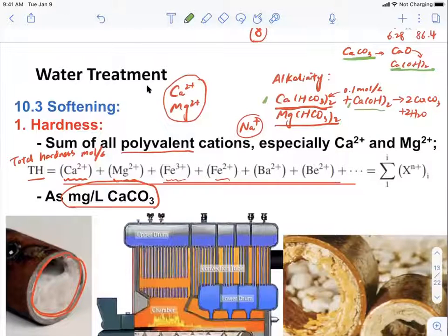Okay, so now let's say the water treatment company knows the hardness of the water, right? And they can directly call the company which sells calcium carbonate. Let's say you just give me 1 ton of calcium carbonate, right? If you represent them as the concentration of calcium carbonate, that's why I would prefer to use this equivalent mass concentration here, to calculate the hardness of water, right?